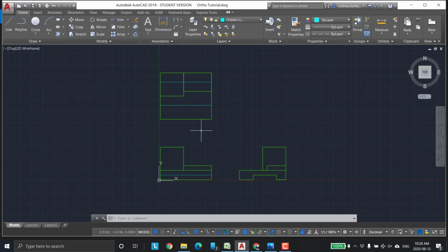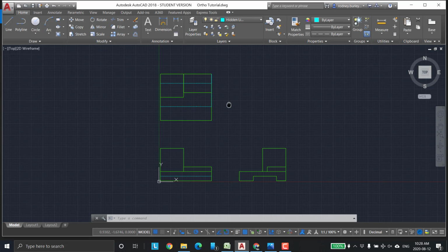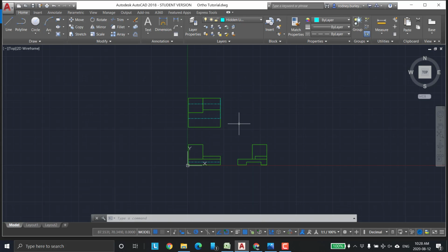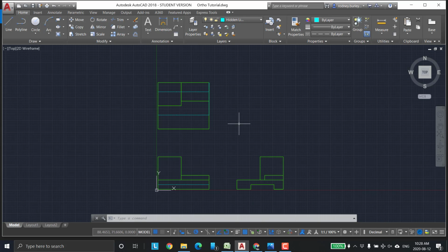You also try to keep the drawing as simple as possible. You try to keep your dimensions in position so they're not all convoluted. You wouldn't dimension everything on this. You try to dimension maybe the width of the slot over here, and then this dimension would go here, and so on. So you try to keep your drawing clear and concise.